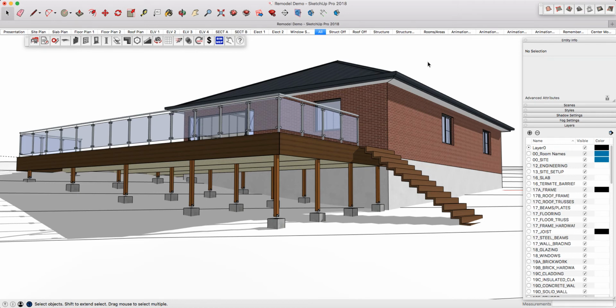Plusspec for SketchUp allows you to analyze structure very easily. And you can do it automatically as soon as you've generated the scenes using the Plusspec scene tool. Scenes are views that you're going to be using to automatically create your 2D drawings, but they're also modeling scenes so that you can obviously strip back your model, check out structure and how everything's working and start detailing, as well as using it for your estimating and bill materials, etc.